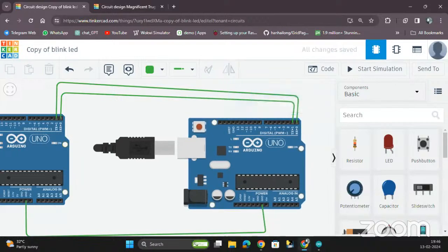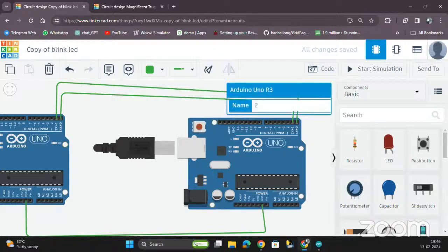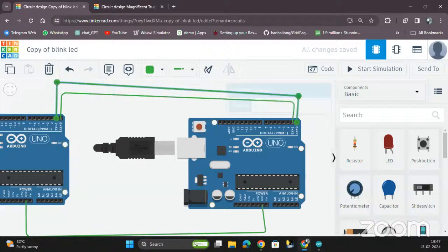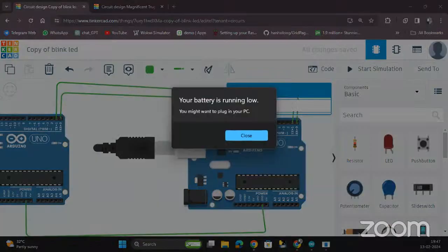So every UART communication has swapped pin connections, like TX to RX and RX to TX. The data is transferred from the first Arduino to the second Arduino through this TX to RX wire.